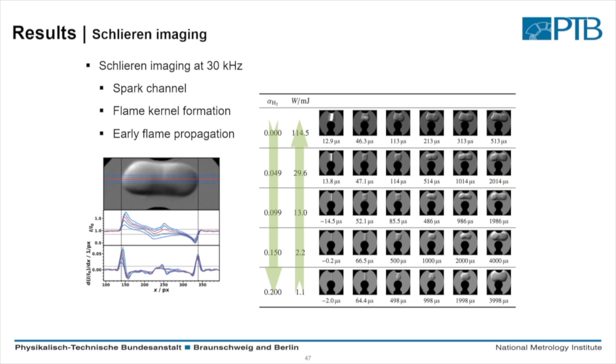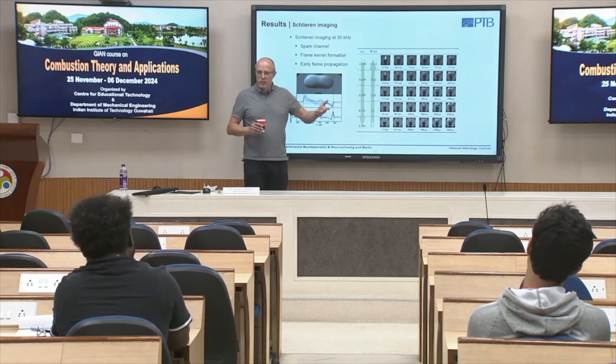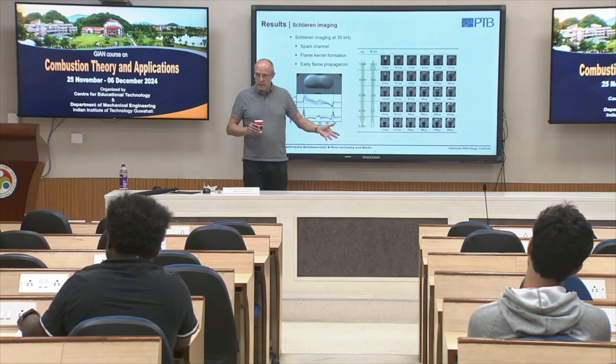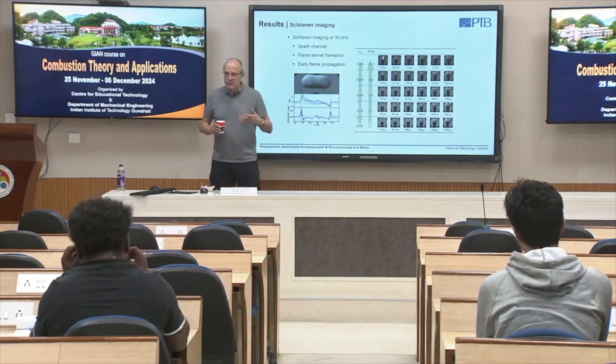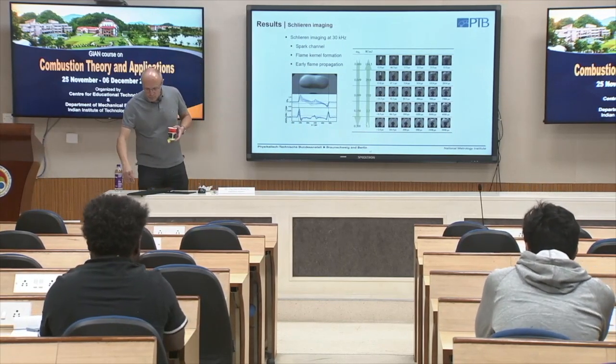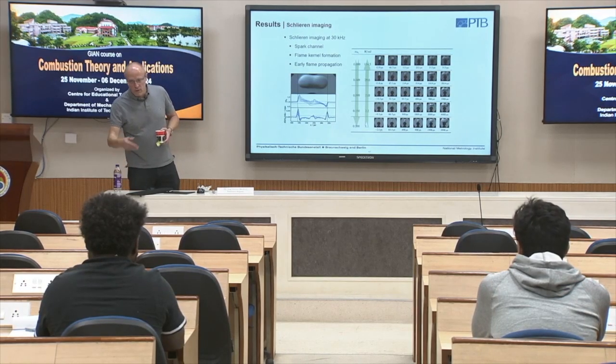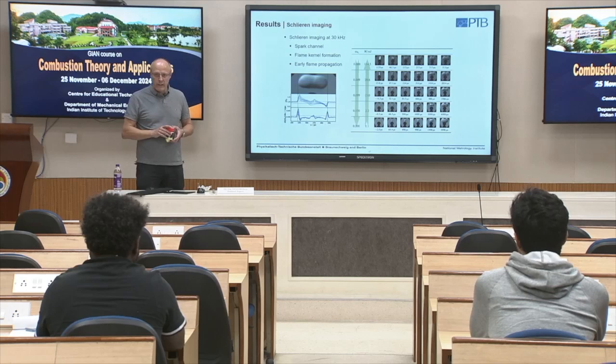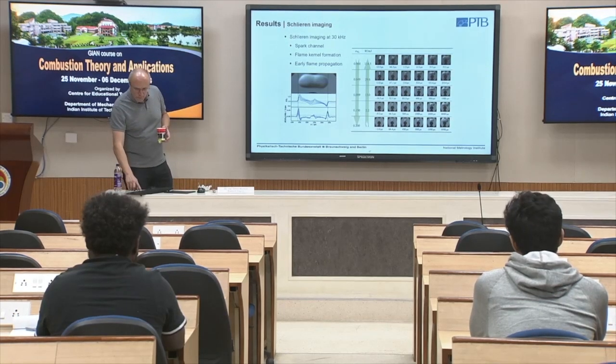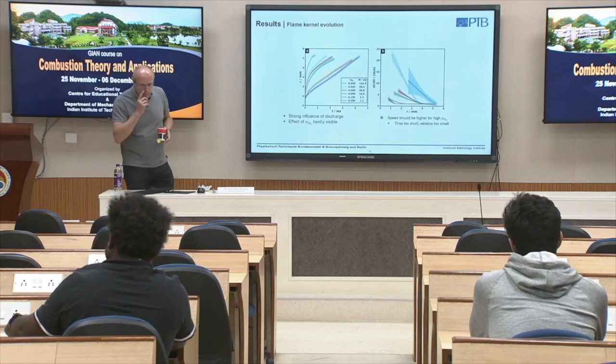Okay. That means here the ignition happened earlier. That's difficult to say. That's the disadvantage of Schlieren. We cannot separate between hot gas from this plasma and hot gas from combustion processes. We see only hot gas. So we would eventually need OH LIF, or maybe better NH2 LIF, if possible, to see clearly where the flame front is.